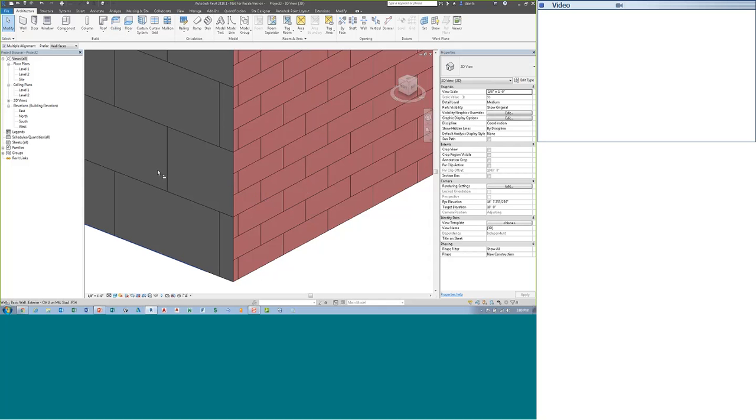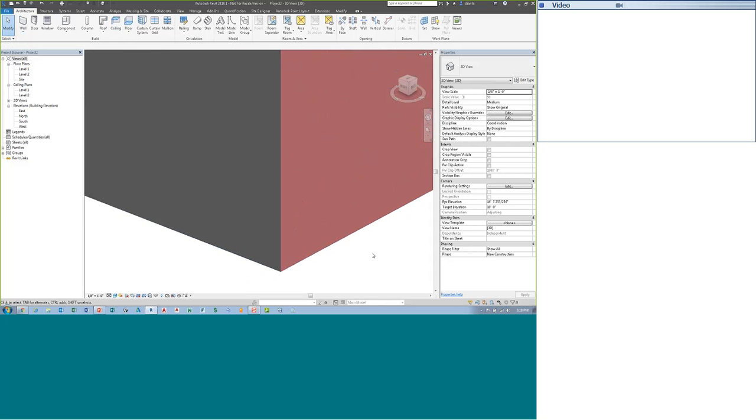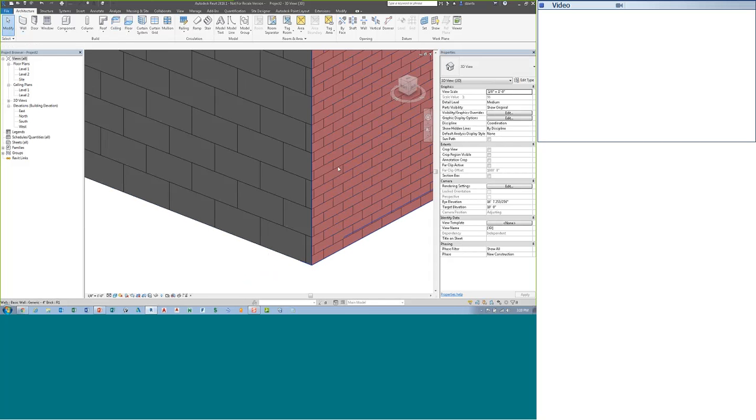What you do is you start the align command, AL is the keyboard shortcut. You'll tab into that horizontal line of that pattern. Then tab into, and sometimes you have to tab in, sometimes you don't. But if you don't, it's good, it's recognizing. I can click this line of this brick pattern, and it moves it up. And then I can lock that relationship if I need to.